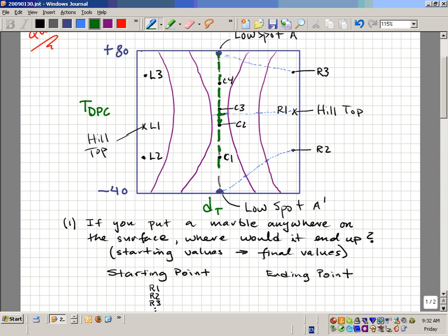Most likely it will take one perturbation in one direction. Which direction? That depends on the optimizer. Some optimizers take perturbations in the negative direction and some in the positive direction. Exactly. So it's not the method of solving, it's which direction you take the derivative in. You're at a point there, and you take minus delta t or plus delta t. All of the other algorithm of the solver could be absolutely identical.